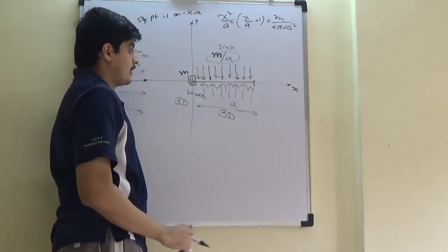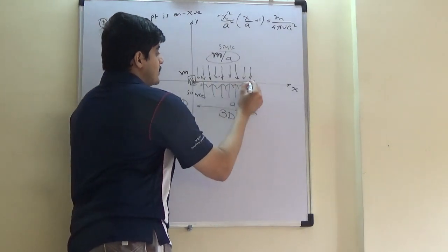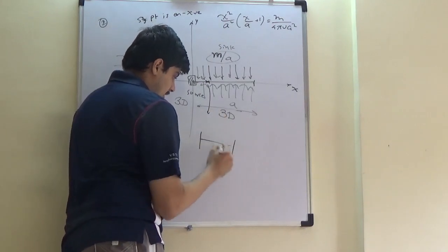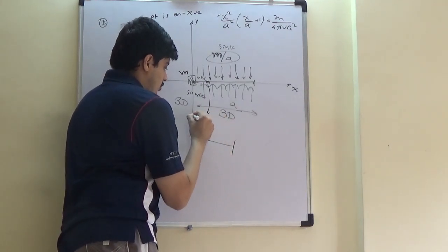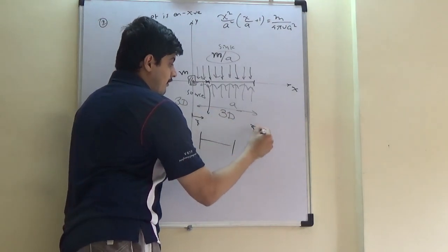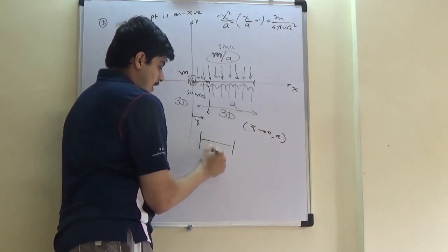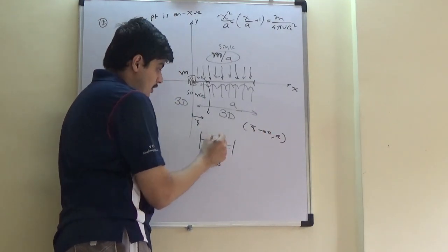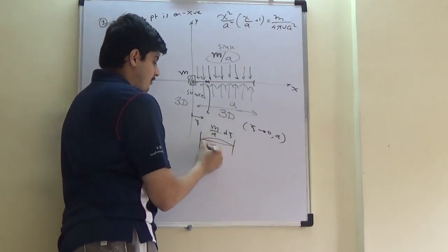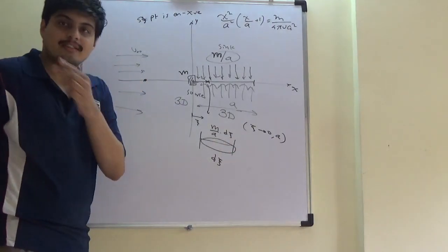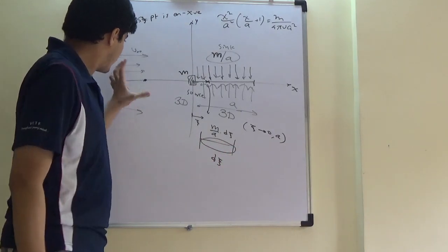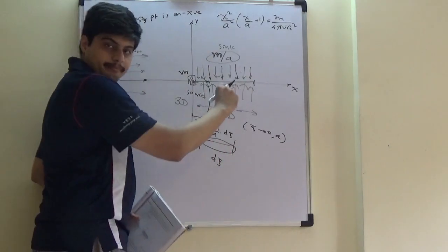Similarly, sink. Now, a sheet of sink means that every infinitesimally small portion, if I zoom this portion here, right, of say, so let's start calling this a coordinate frame zeta, right? Zeta varies from 0 to A. An infinitesimal small piece d zeta would have strength, this. Now this acts, infinitesimally small, like an individual sink. And what is it going to do? Individual sink is going to suck the flow.